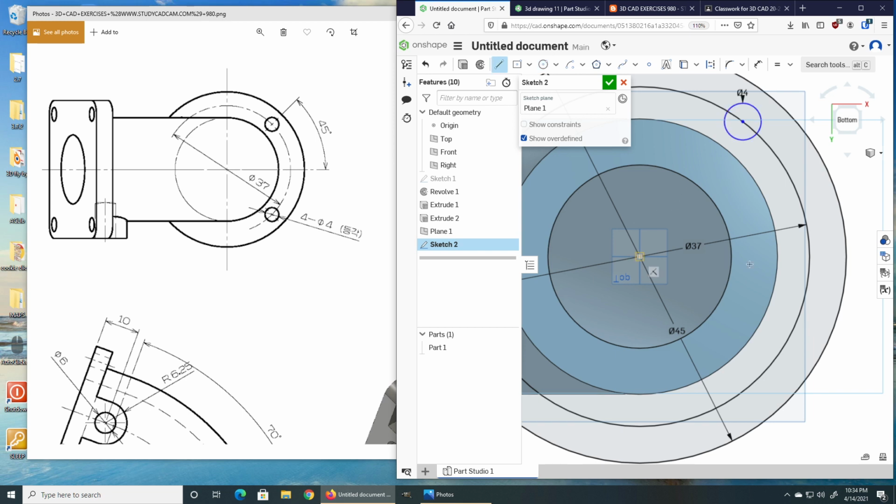Now a line from the center out. Might as well just go here and stop. I went horizontal and coincident. That's very important. I was paying attention to when those points were going to lock in. That's why this line is black and not blue. My circle is still blue because it doesn't know where it is. It just knows that it's on this line somewhere.